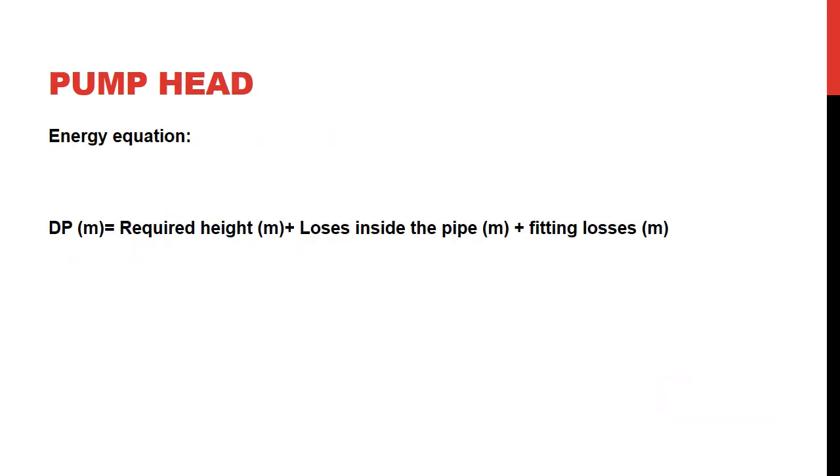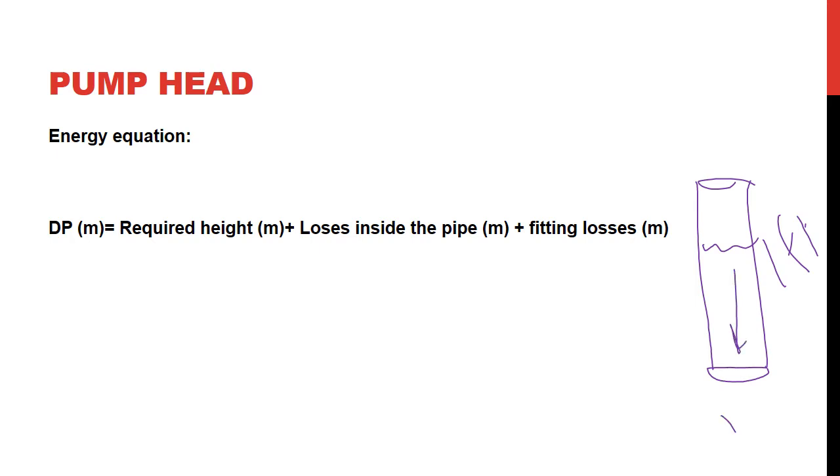Okay, let's explain what pump head is and why it is required to be calculated in such a manner. What is the feet of water? If I have a tube, and this tube is filled with, let's say, 1 foot of water, this water will exert pressure on 1 square inch. If the area of the base of this tube is 1 square inch, and I have the water weight acting on it, this water weight per 1 square inch is called 1 foot of water. So this is why we have feet of water.